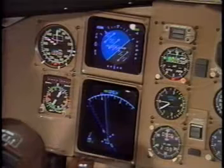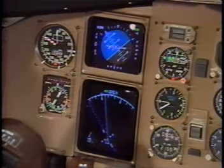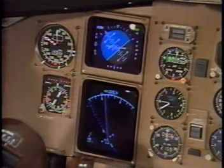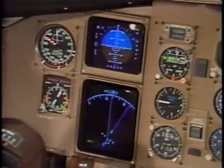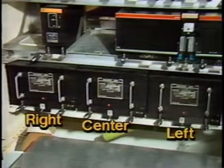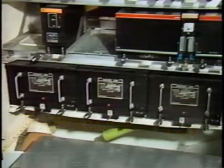The test values displayed on the flight instruments and IRMP data display stay on as long as the front panel-mounted test switch is pressed. When the test switch is released, the interface test terminates and the IRS returns to normal operation. A similar test can also be performed for the right IRS. The test data displayed on the First Officer's EADI, EHSI, VSI, and the Captain's RDMI is the same.